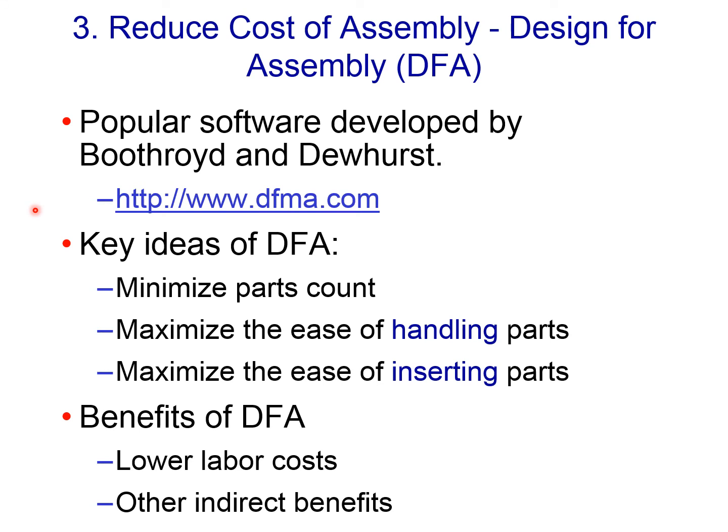They specifically focus on the handling and insertion in their DFA software. But how the parts are made is another module. So in this slide we're going to talk only about handling and insertion. Benefits of this: if I'm going to make assembly easier, which means faster, then the labor costs of assembly are lower. That is the direct benefit.